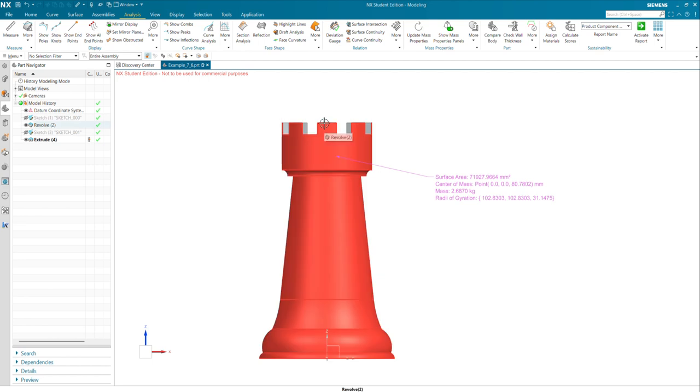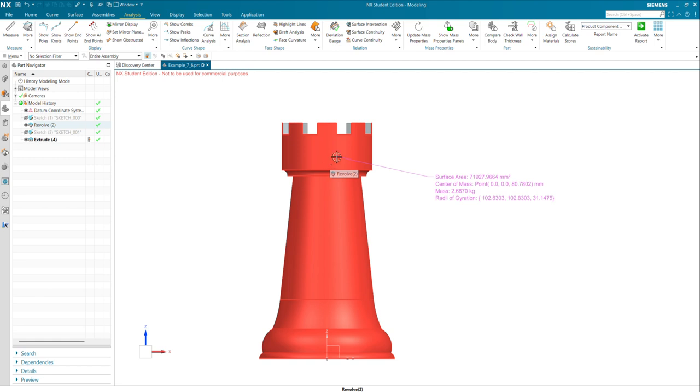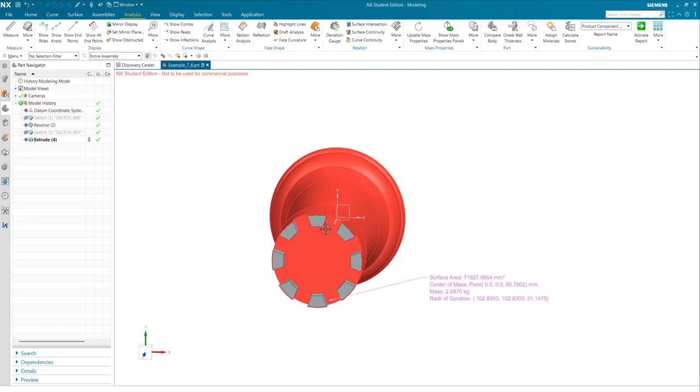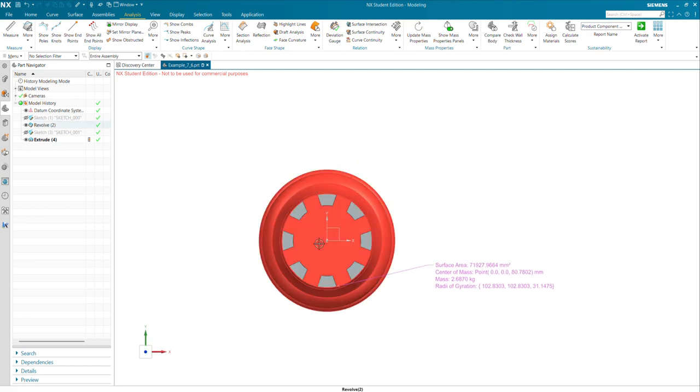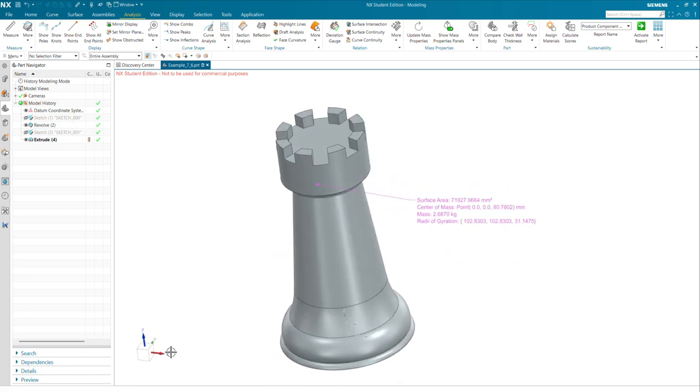Important to remember, you don't create this entire outline and then try to revolve it. You only create from the point or the vector that you want to revolve about one side, and then you revolve that entire curve about that point. So it goes around the sketch origin or the point you've selected. So for instance, if I've selected the x-axis as the vector of rotation, it would have rotated around the x-axis, so like that. So that's quite easy.